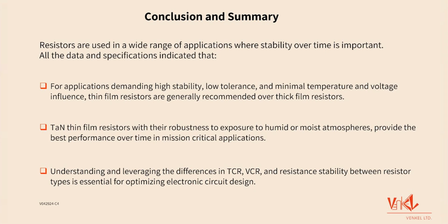Resistors play a critical role in electronic applications where stability, precision, and durability are essential. Based on the data and specifications reviewed, thin film resistors emerge as the preferred choice for applications demanding high stability, low tolerance, and minimal sensitivity to temperature and voltage changes. Their superior performance makes them ideal for precision circuits in industries such as aerospace, medical devices, and telecommunications.